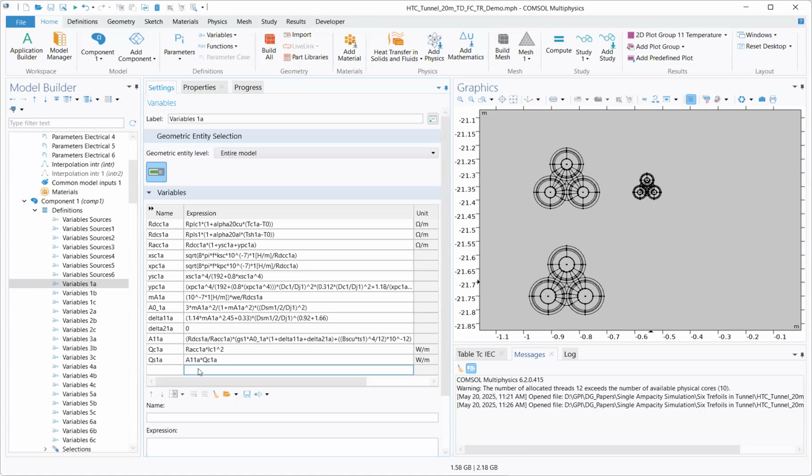Because now, if you're going to go into eddy currents and all these things, your meshing needs to be very fine to allow the eddy currents to be properly modeled in the solids. Still, because the cables are stranded, you're not going to put a stranded cable here. It is going to just kill your simulation.